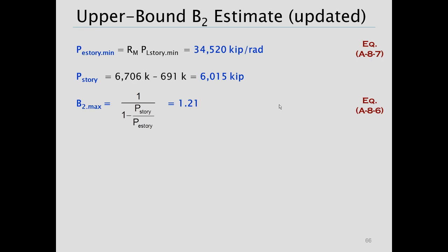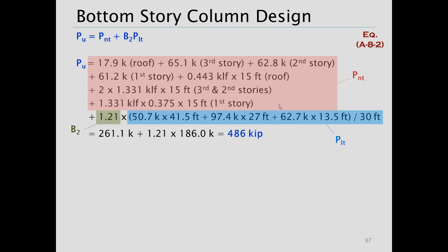Now, if you have a building that has a particularly larger side sway amplification, as you may have sometimes for moment frames, then it can be very beneficial to use this procedure to get yourself a little bit of a break in terms of what we would design our structure for in terms of overall side sway amplification effect. All right, well, let's take that and run with it. Let's design our bottom story column.